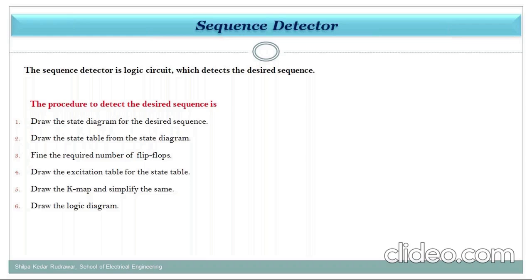So if the base, that is the state diagram, is wrong, whatever you have designed is wrong. The one hour or half hour you spent drawing that diagram or implementing that circuitry will be wasted. So always concentrate and check that state diagram twice before starting implementation.